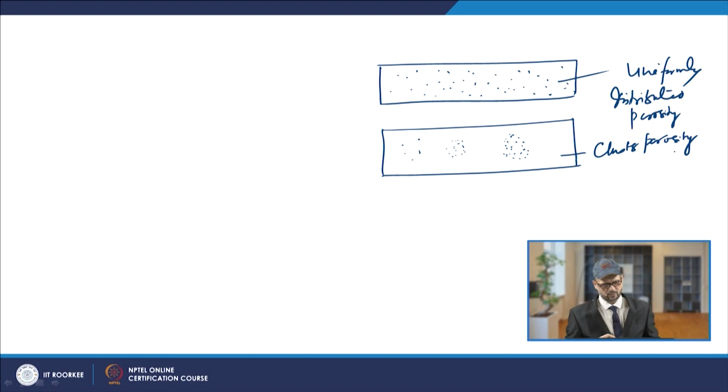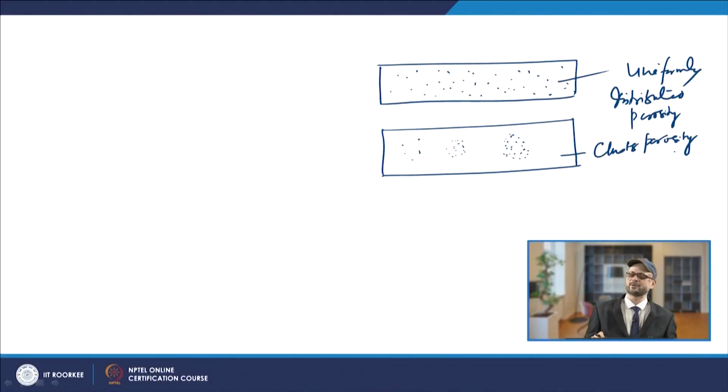They are basically because of the change in the welding conditions, like changes in the arc settings. Because of that, these cluster type of porosities come up, or sometimes, many times, you stop the welding. In those cases these cluster type of porosities develop, and these are basically not very good for the welding. Similarly, you have the starting porosity.